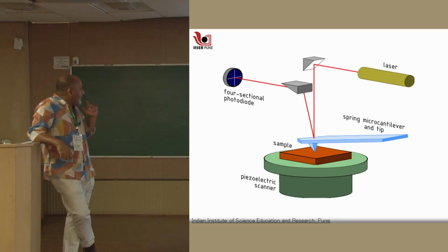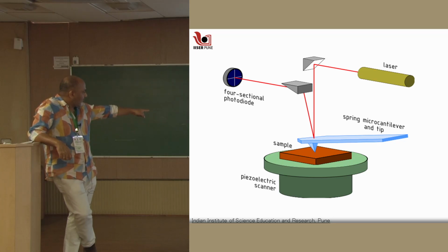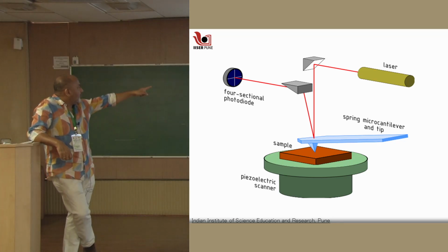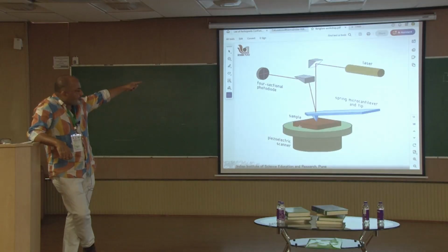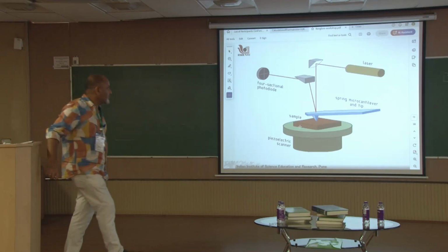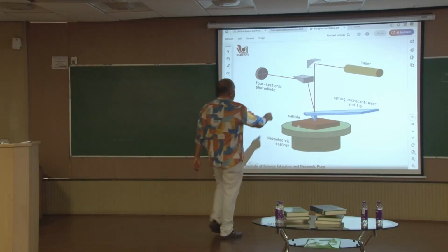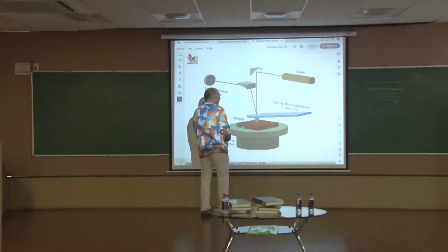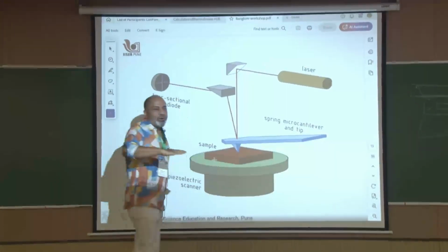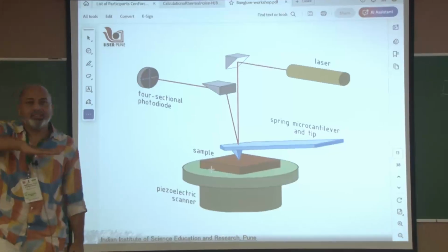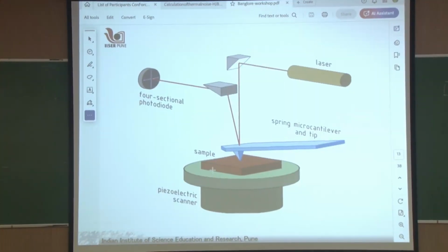And the idea behind this is quite simple. What you do, you have a cantilever like that, substrate and scanner and everything. You got a laser that goes into a mirror. So that mirror sort of vertically brings the laser down. Okay, so this is horizontal. It will bring this down vertically. You always deliberately have about a 12 degree angle in the cantilever. And why is that? Can anyone say?